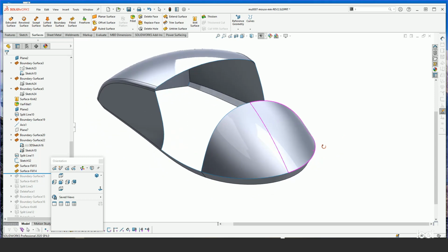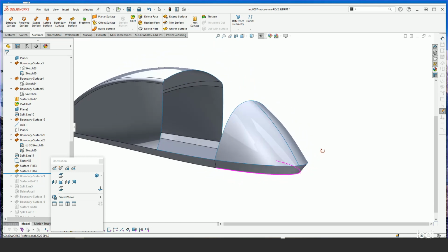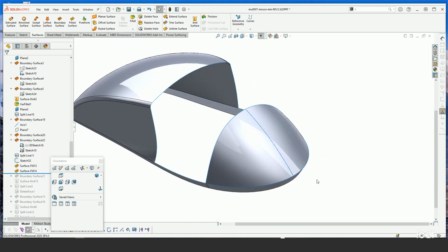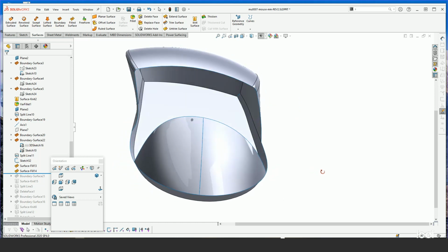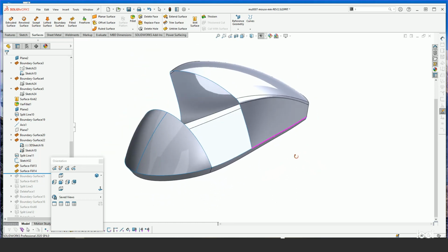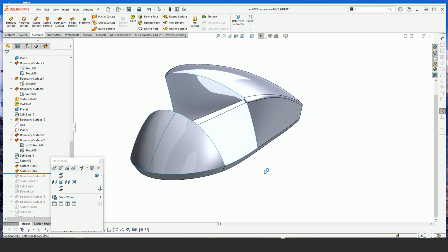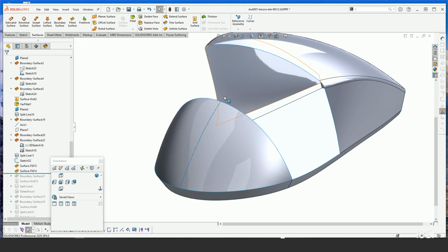And really with this kind of surface, as it is a 2 or 3-sided surface, it needs to be done with a fill versus a boundary, and I've talked about that in previous episodes. So before I do this fill surface, as you know with fill surfaces from what I've already shown in previous episodes, they work best when you can constrain them to tangent boundaries, and that is reference surfaces.